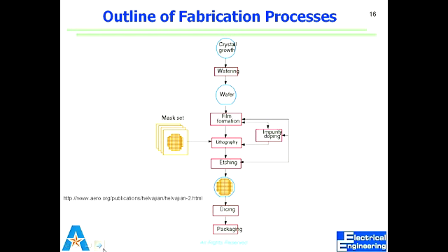But there's an interesting side note. If I'm a process engineer, I know how all of these things happen. But when I go into a fab, I have to know my machine, which means I have to run several characterization runs to know the behavior of the machine. The paper says for 10-minute oxidation I should get this amount of oxide, okay, now I'll do it myself and see what I get. So I have to characterize the equipment and the process before I do it on a master wafer or master batch. All those steps have to be characterized.